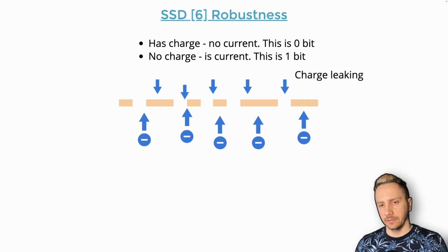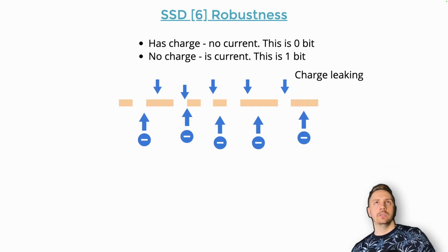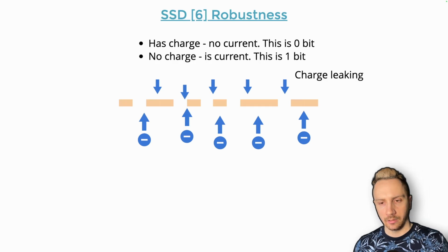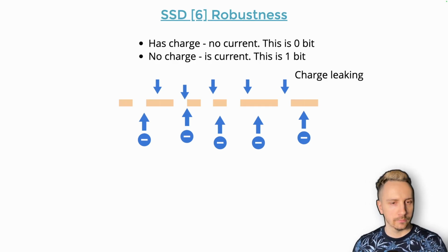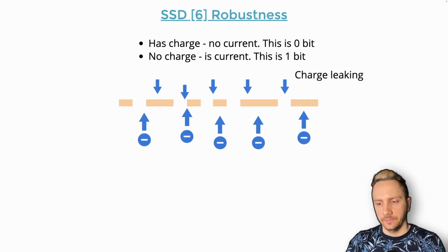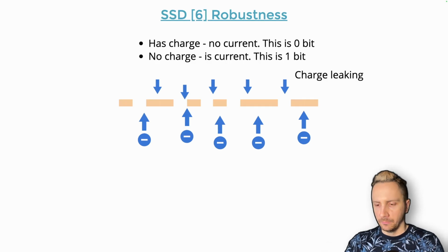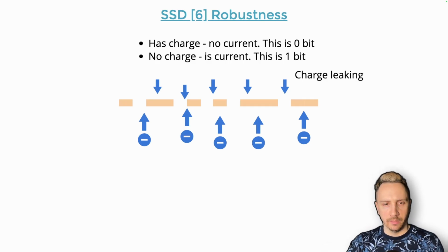When SSDs are manufactured, usually it's known relatively precisely in advance how many writes they can do in total, like some millions of writes or whatever. After that, the data might get corrupted, and I think some SSDs can even detect that and slowly mark some segments of their memory as unusable if it degrades over time.